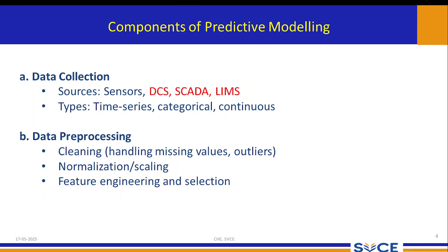What are the key features of this DCS system? Distributed control: functions are distributed across multiple controllers, improving system reliability and making it easier to manage large complex processes. Real-time monitoring and control: DCS provide real-time data collection and processing, enabling operators to monitor and control processes effectively.